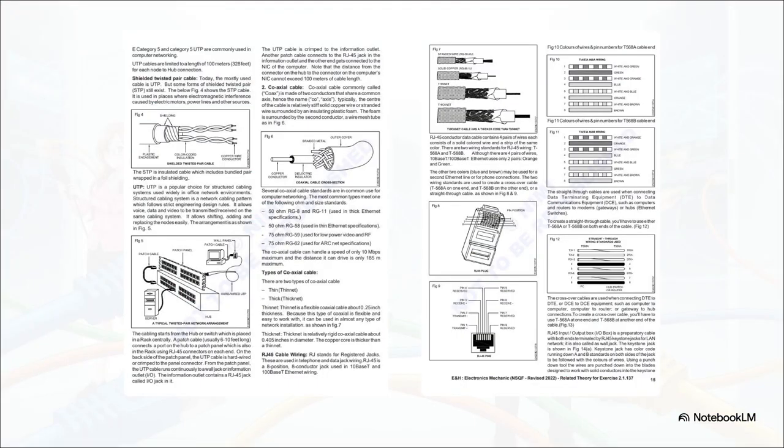When you visually lock in the internal coax structure right next to the physical footprint of ThinNet and ThickNet cables, you can really see how much more robust that ThickNet copper core is. Keep in mind, though, standard coaxial networking generally taps out at speeds of 10 megabits per second, with a maximum drive distance of 185 meters.